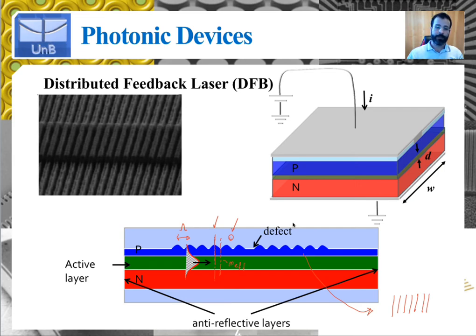It's also important to note that for most devices you also have to apply some anti-reflective treatment on these surfaces at the facets of the chip, right? So usually you have additional multi-layer structures deposited on either facet in order for these to transmit 100% of the beam at the Bragg wavelength, because otherwise these two surfaces right here would form two additional mirrors, and you would have an additional cavity which would interfere with the cavity which now is the distributed Bragg reflector itself. You don't want an additional cavity outside the cavity that constitutes the cavity of the laser itself.